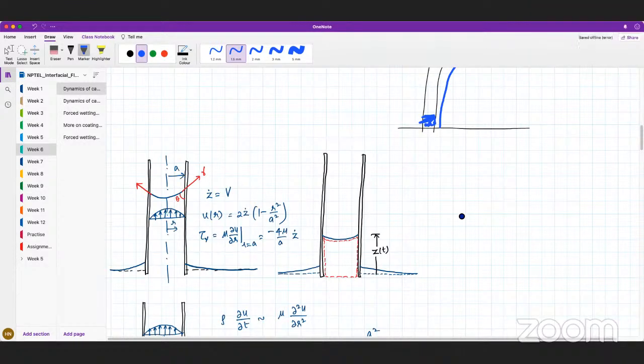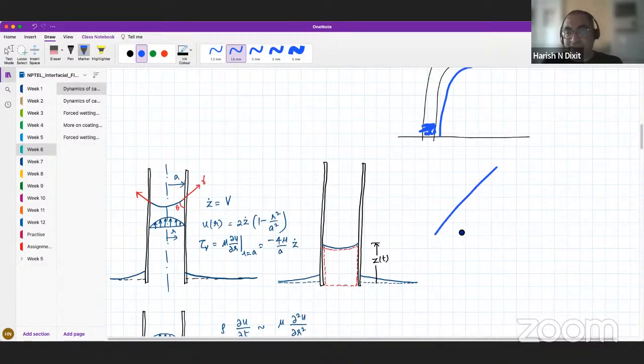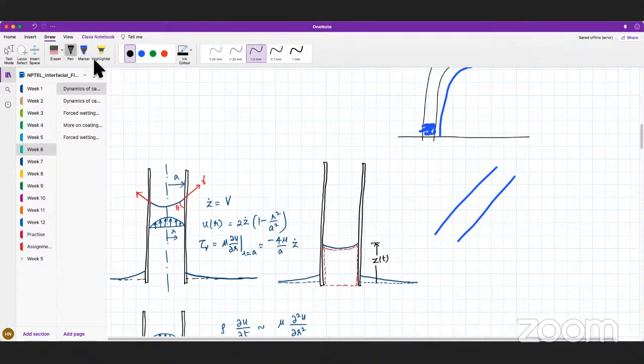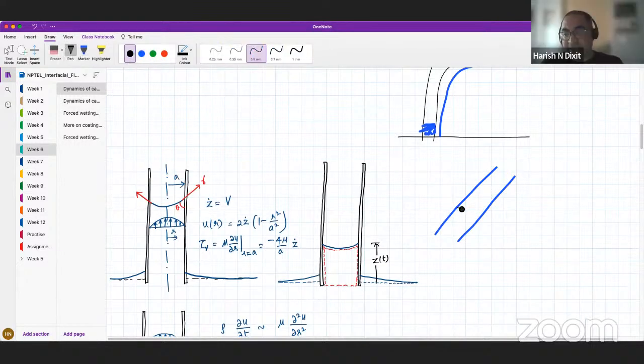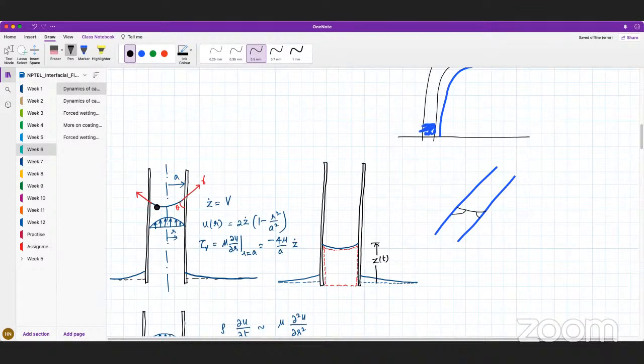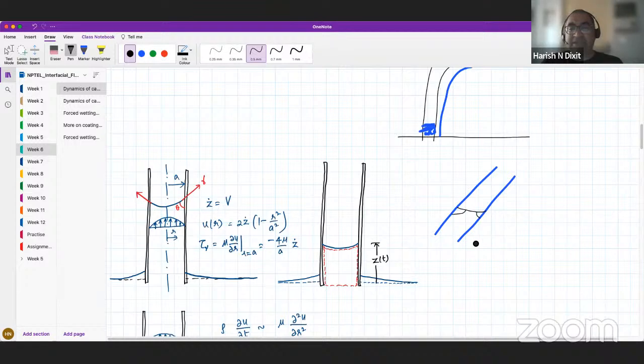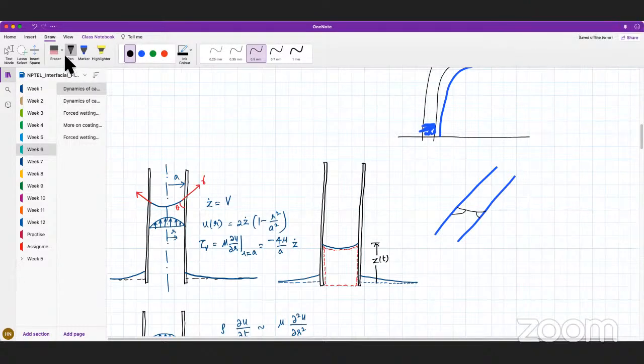Imagine if you have a tube that locally is like this. The tube is basically inclined locally, and now you have an interface like this. The angles here and here will be different. So determining the surface tension force will itself be tricky, because the contact line is not a circle. It's basically a three-dimensional curve, because it's on this boundary.